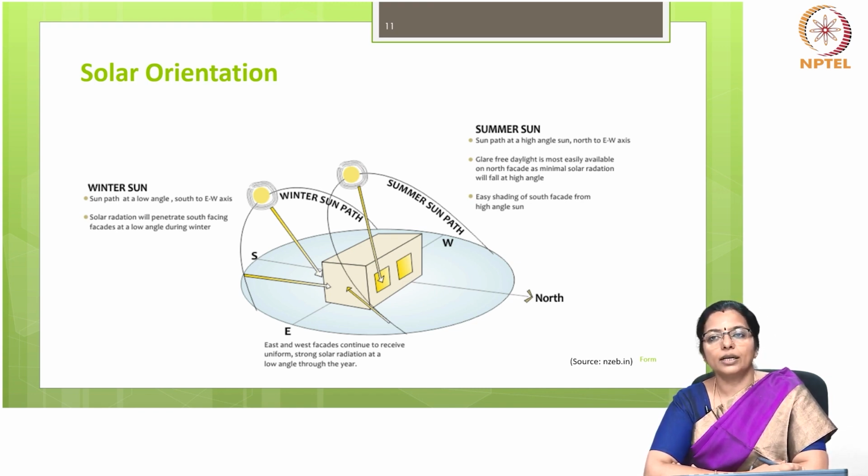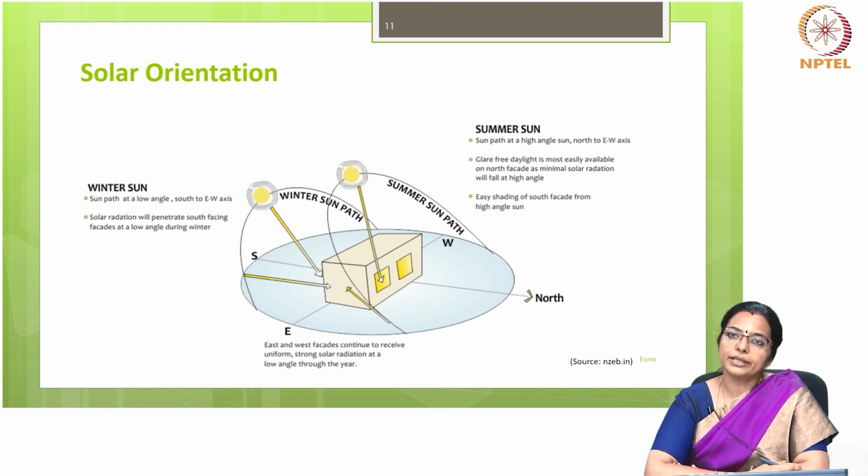On the other hand, during the summer, when the sun is higher and more intense, buildings need to minimize solar heat gain to maintain comfortable indoor temperatures. This can be achieved by using shading devices such as overhangs, awnings, or louvers on the southern side to block direct sunlight. Ventilation can also be incorporated to enhance cooling without relying heavily on mechanical systems.